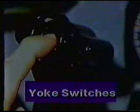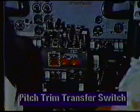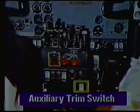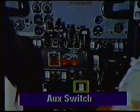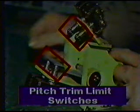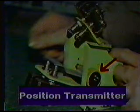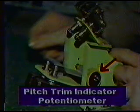They are usually further identified by position as well, such as pilot's pitch trim switch. The dual mechanically ganged switch assembly located in the pedestal is called the pitch trim transfer switch. The single switch located in the pedestal is called the auxiliary trim switch, or aux switch. The switches located in the vertical stabilizer are called the pitch trim limit switches, and as an assembly is sometimes referred to as the birdcage. The potentiometer installed in this unit is called a position transmitter, or pitch trim indicator potentiometer.